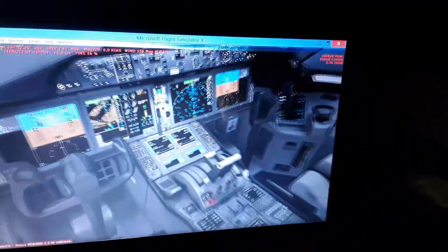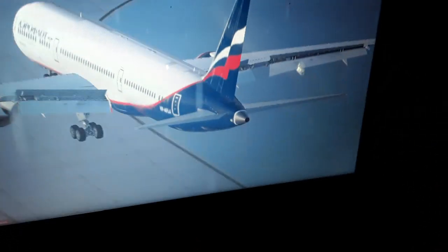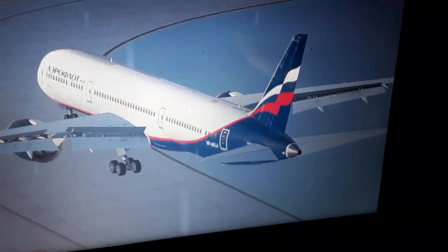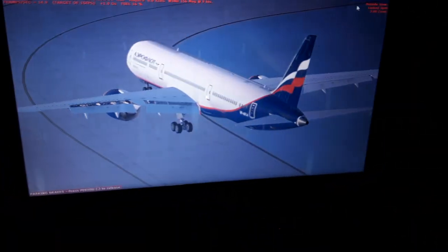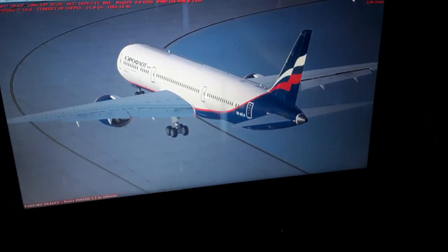So you can see here we have the flight controls. So we can climb like this, control the elevator, the horizontal elevator, climb, descend, also the rudder, use the rudder pedals, and the ailerons and the spoilers, the left and right turns. We have the flaps extended, so this is the control axis. You can use also the horizontal stabilizer trim for the elevator when climbing, descend.